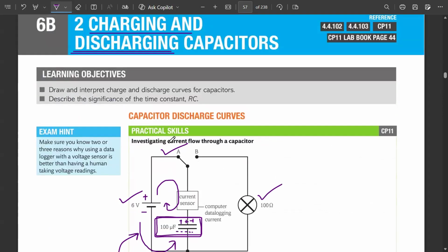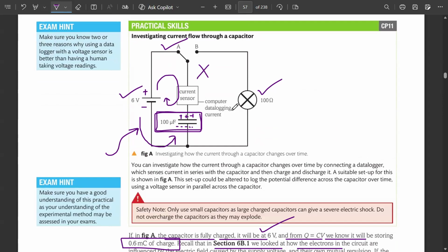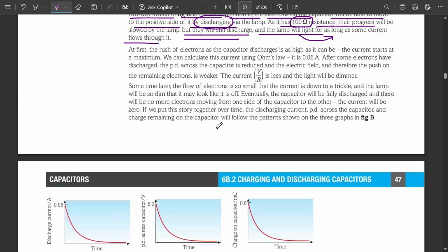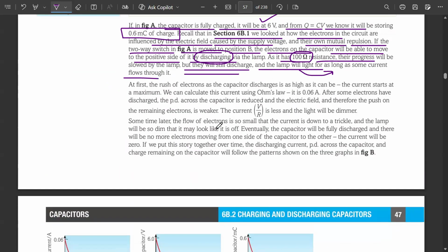Even if you close this circuit, what will happen? Will the lamp switch off immediately? No. It will light on for, let's say, a few seconds or maybe a few milliseconds. Why? Because there was some charge already stored in this capacitor that is being used to keep the lamp on after the switch was opened. So after a few milliseconds, when all of the energy and the charge from the capacitor has been used, the capacitor has been fully discharged, and the lamp will go off after a few milliseconds. Now when the circuit comes back, when the power comes back, the capacitor will charge again.